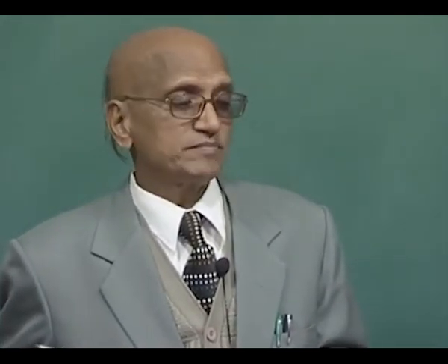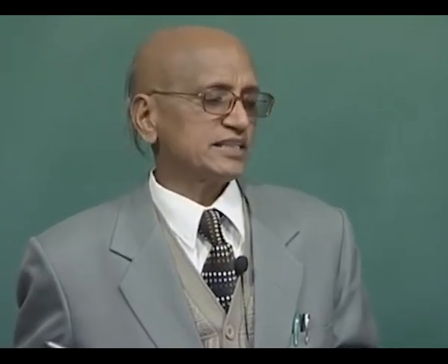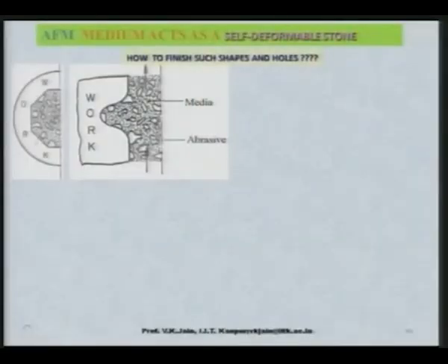This is the abrasive flow finishing process, where you have a viscoelastic medium mixed with abrasive particles, viscoelastic material, additives, etc., that will pass through very fine cavities or very fine features like this over here, and when the abrasive particles come in contact with the surface, they shear off the peaks of the surface and give a very good surface finish. If there is a concave shape like this, this particular process can easily finish it. As you can see, the medium is moving like this, and it will be able to finish the cavities as well as plane surfaces or cylindrical surfaces.